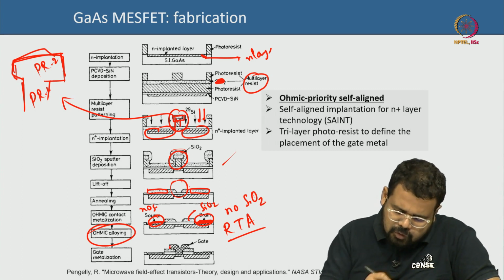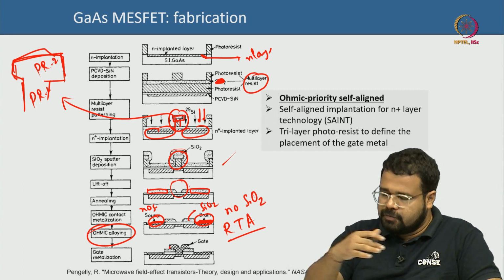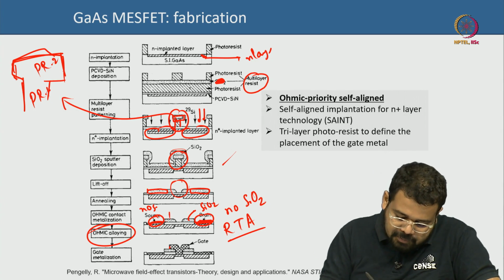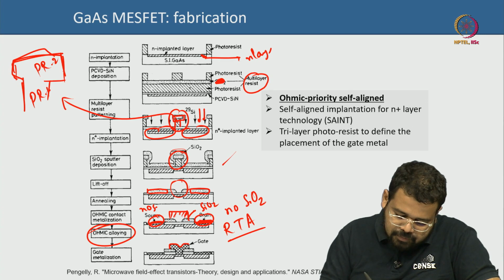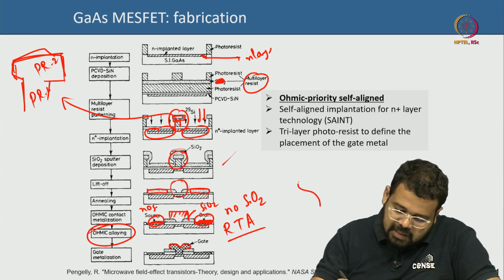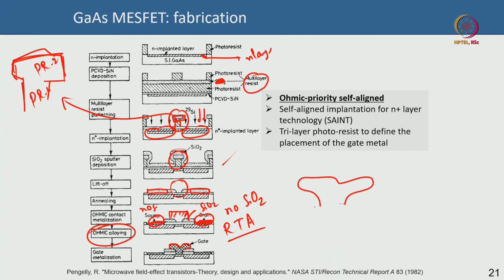You do a photolithography process, you define the pattern, you open the photolithography process in this region, so that whatever metal you deposit will take the shape of this. So, eventually your gate looks like that, metal, this is your gate metal. Okay. And it need not be silicide or tungsten or some kind of a refractory metal, it could be titanium gold for instance. And then you have the passivation, silicon dioxide around it, silicon dioxide around it.